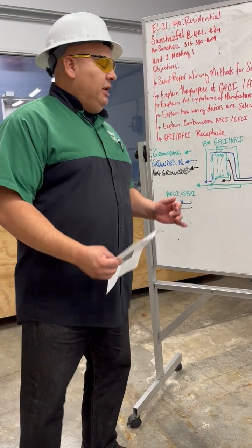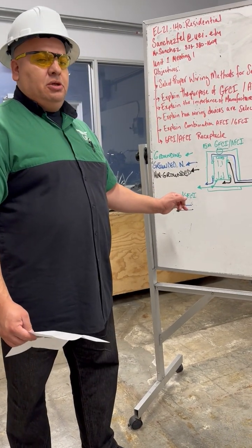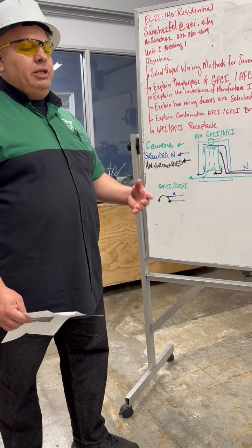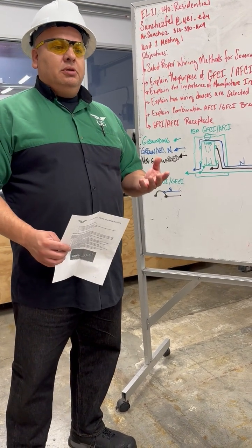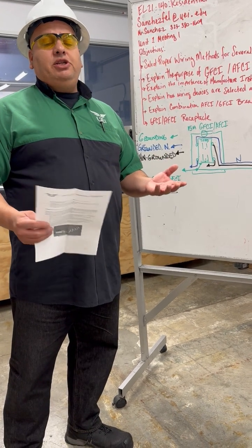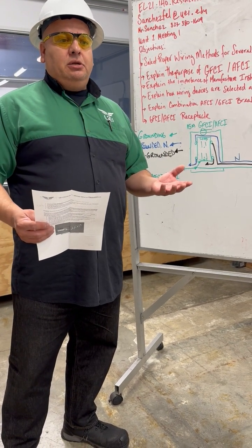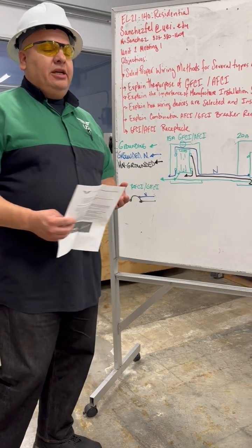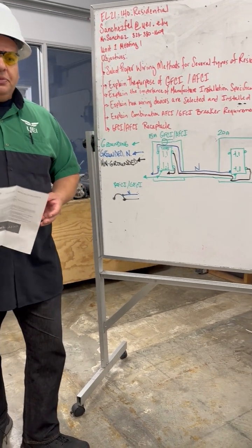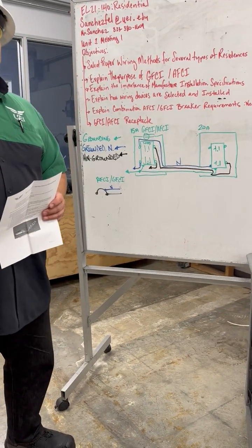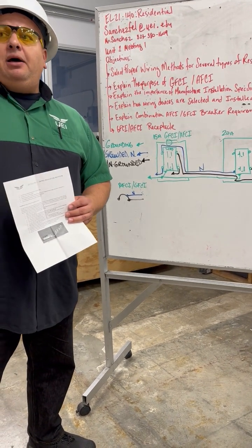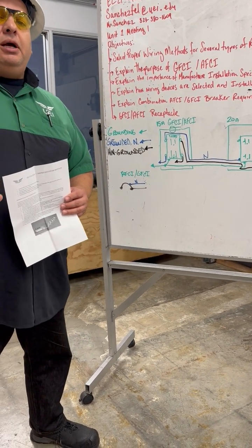It's going to be starting at the circuit breaker itself, and how those circuit breakers are either, I'm going to say, generation 1 AFCI combination breakers, which have a pigtail for the white neutral. The second generation of those AFCI, GFCI combos have a plug-on neutral. Obviously, we have to have a panel that accompanies the plug-on neutral concept.